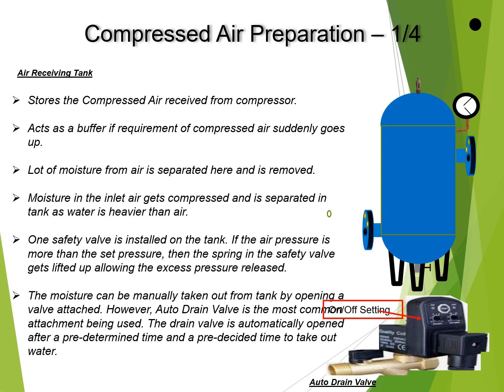This tank is also having a safety valve. If the pressure of the compressed air inside the tank crosses the set value, then the safety valve operates. It is spring loaded. The extra pressure is released from this valve.